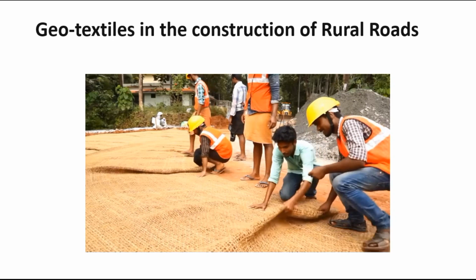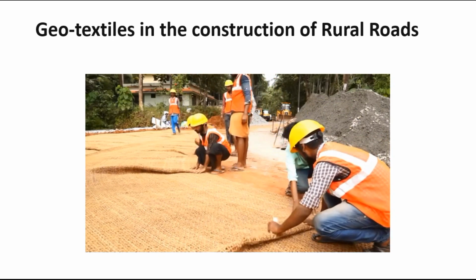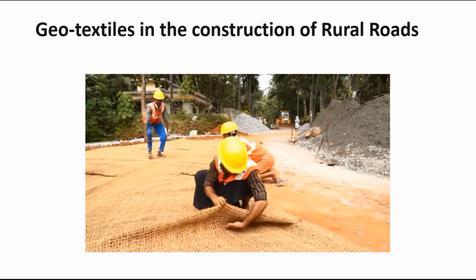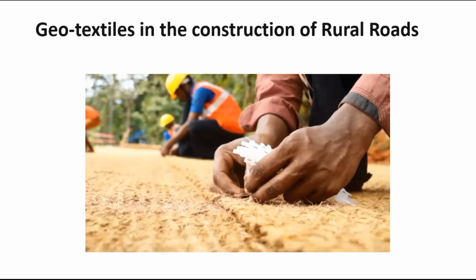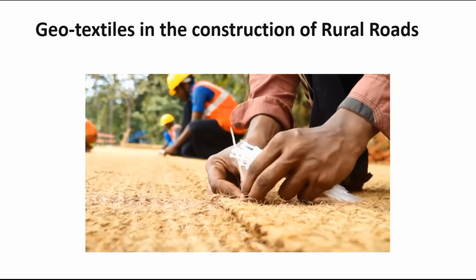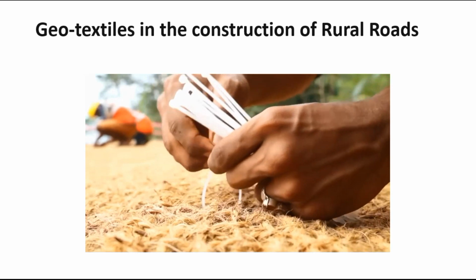The geotextile needs to be folded properly, not for full width, to account for the difference in length along the two edges, inner and outer, of the roll curves. Thereafter, each roll is tied at the overlaps using cable ties at a spacing of not less than 1 meter.